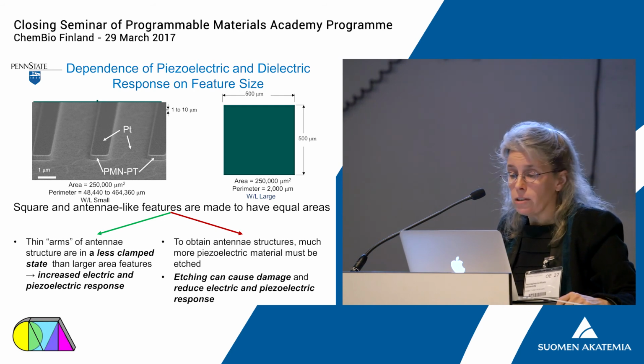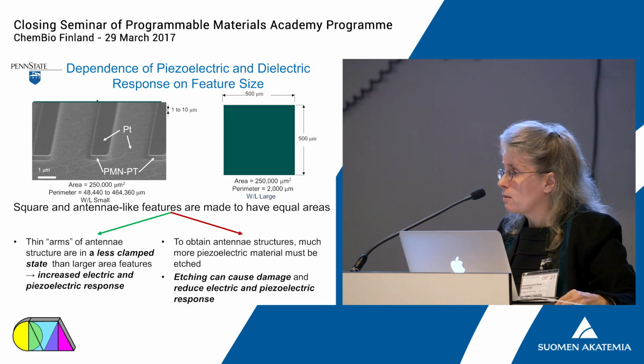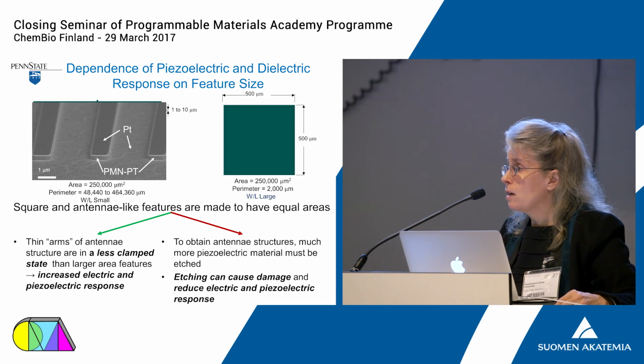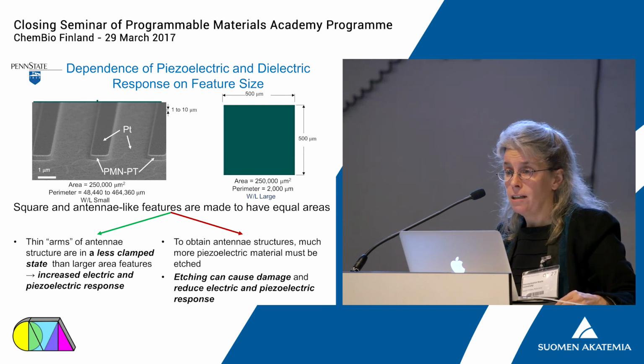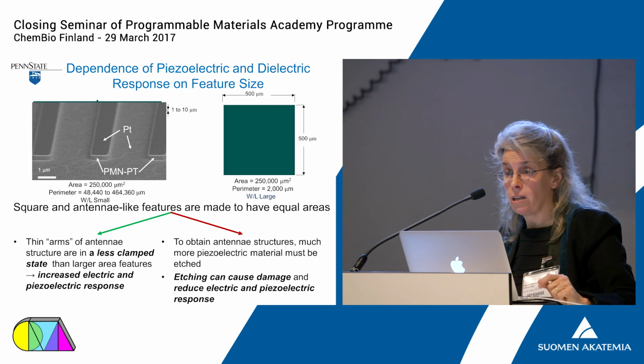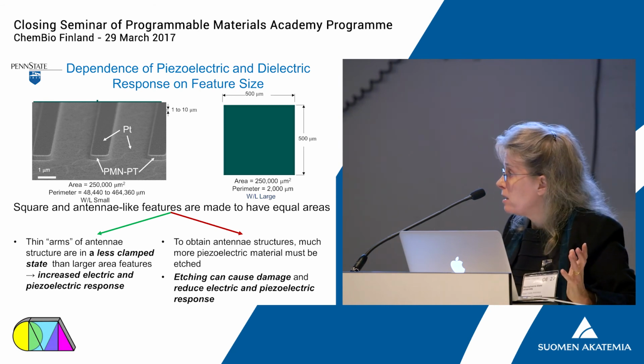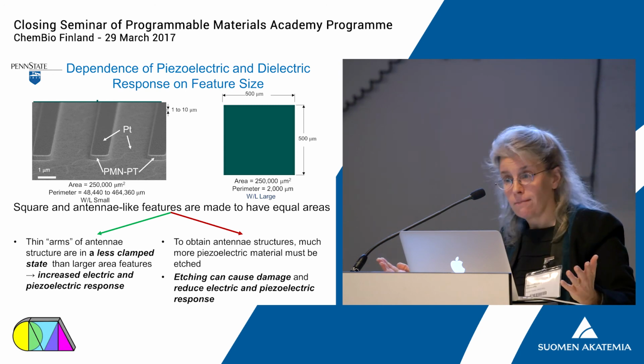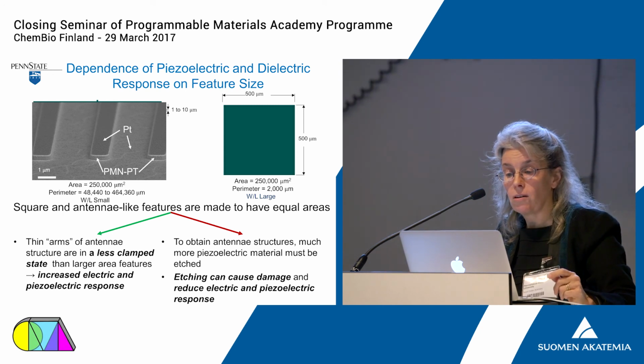The less ideal situation is these are all complex oxides. Start with 4 cations. If you mess up the stoichiometry or the crystallinity, the properties go to 0. And so I need to be able to take this complex chemistry and pattern it without degrading the crystallinity or the properties, because if I etch-induce damage, we're never going to be able to do the scaling.